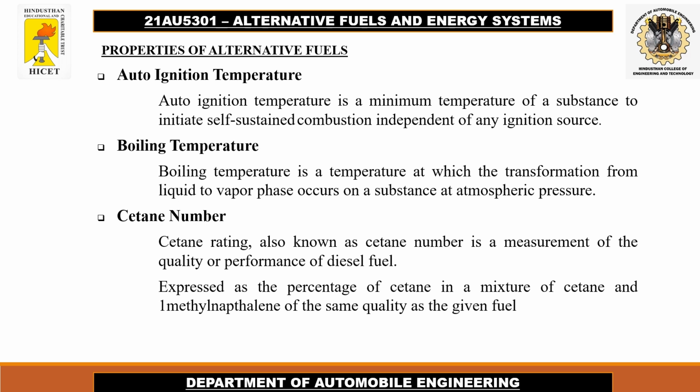Next one, cetane number. Cetane rating, also known as cetane number, is a measurement of the quality or the performance of a diesel fuel, expressed as a percentage of cetane in a mixture of cetane and 1 methyl naphthalene of the same quality as the given fuel.